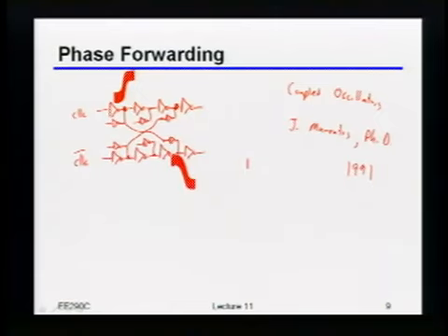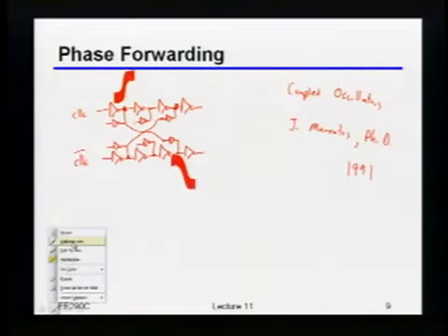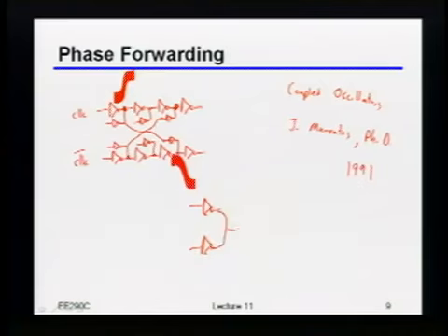Does that make sense? By the way, this is more generally how you do what's called phase interpolation. Let's say you do want something that has a variable delay, or a variable clock phase. What you can do is take 2 clocks, for example, some clock and some delayed version of the clock, and just feed them into 2 inverters. If you short their outputs together, then you'll get something whose delay is somewhere in between the delays of the 2 inputs, okay?